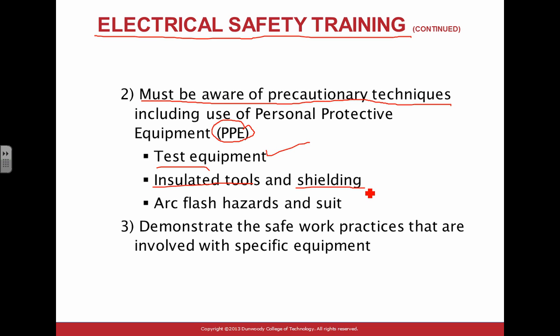So when you work energized, you have to use fully insulated energized tools. I don't know if they enforce it for you guys. These are 600 volt rated equipment. But from a shock hazard, it really doesn't matter because these are protecting you from shock. Remember, they just don't want to shock you. Now this one looks like it's insulated, but it's not rated for insulation. Though if you use it, when it comes to a 20 amp 120 circuit, the amount of energy and the amount of hazard is a little bit low, but still there.